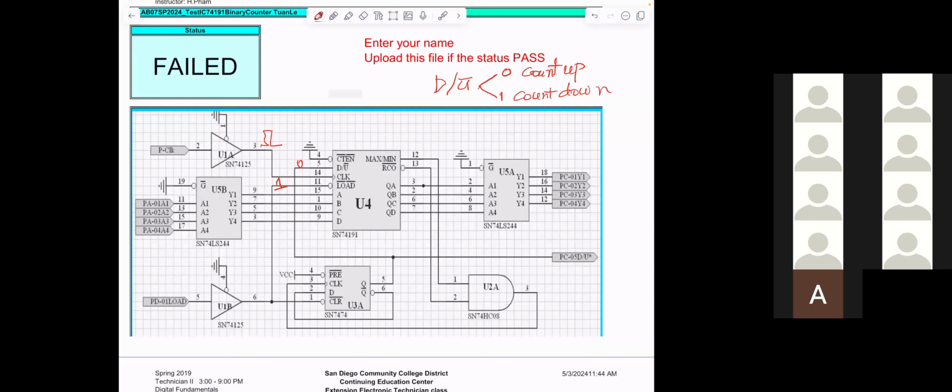However, the output pin number 3 is still logic 1, but they bring it up to about 4 volts. You understand, 4 is still logic 1. However, they want 5 volts, standard logic 1. So buffer means 0 in, 0 out, 1 in, 1 out.